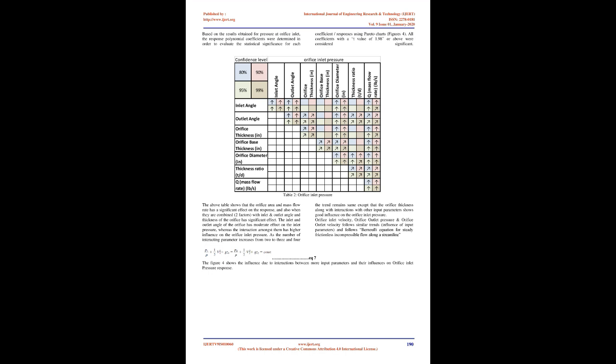The challenge was to define the DOE methods with a minimal number of analyses, to enable DOE modeling with a feasible amount of effort. DOE is chosen to reduce the number of analyses required by ensuring uniformity and to capture all possible combinations of design points. A conventional and useful form of DOE is the factorial design 2^k. This is economical while also effectively covering the entire design space.